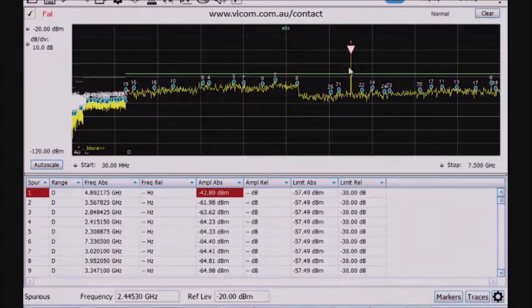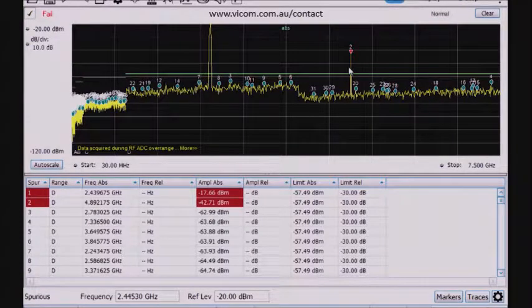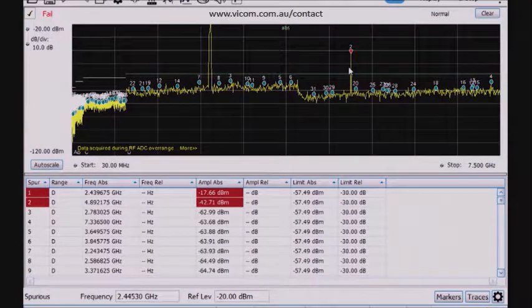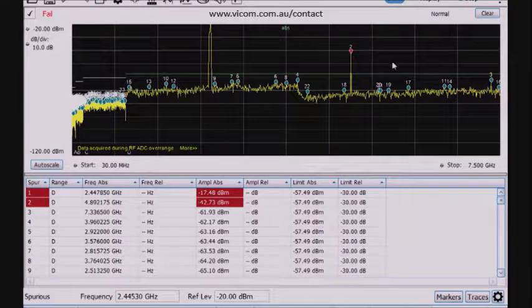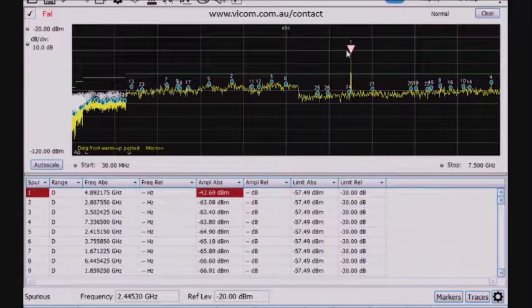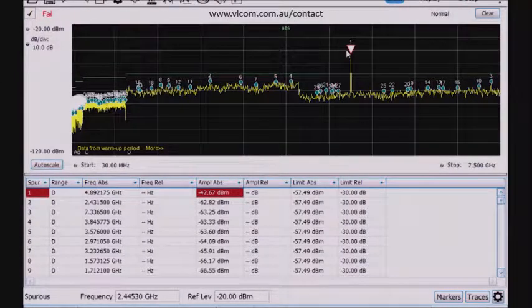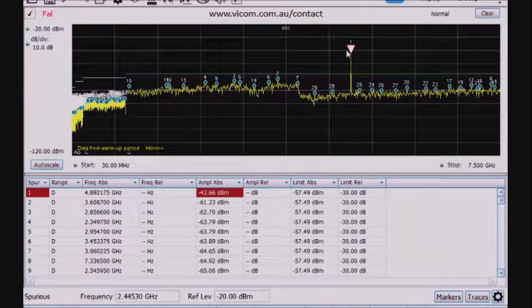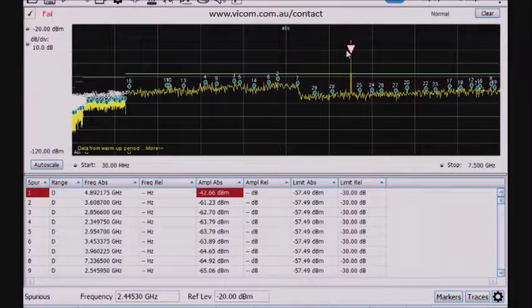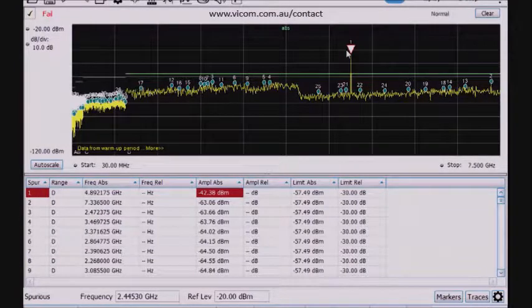This is a good conservative estimate. It gives me pretty good confidence in this case that I would not pass final EMI compliance, particularly because of this second spur here that's always present. So I'll have to go back and look at that design to make sure I can fix anything that's wrong there, maybe add some shielding, or look at the leads. Maybe there's some pickup from a power supply. Somehow I'm getting a second harmonic there that's causing me to fail this EMI pre-compliance test.